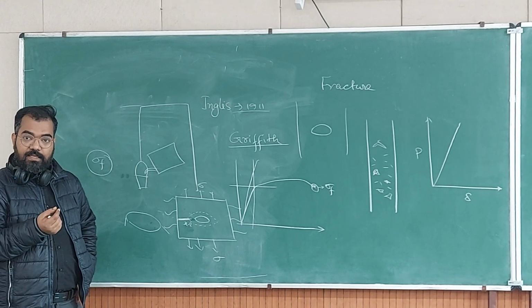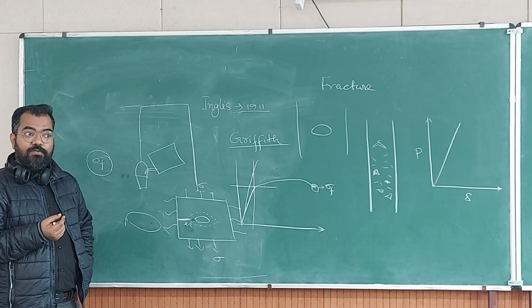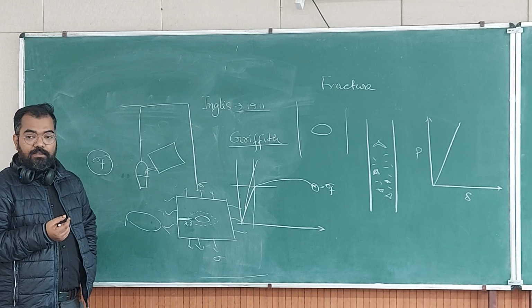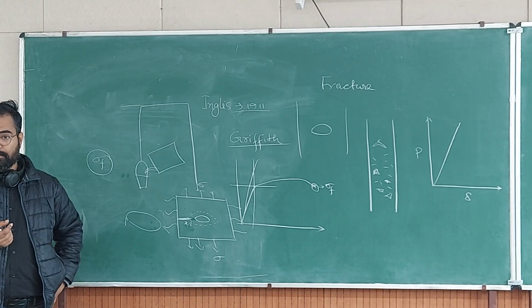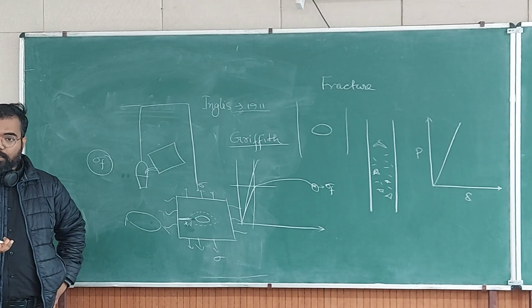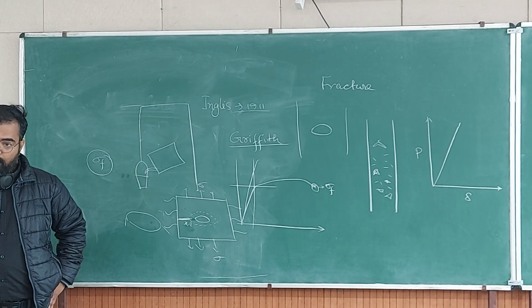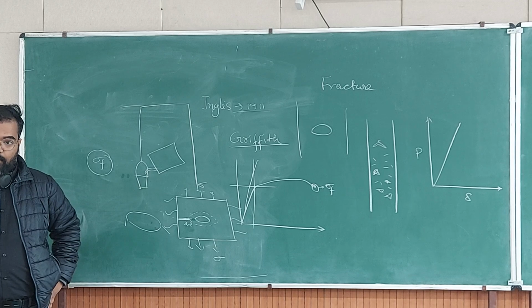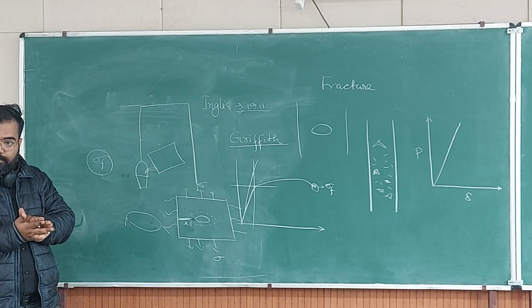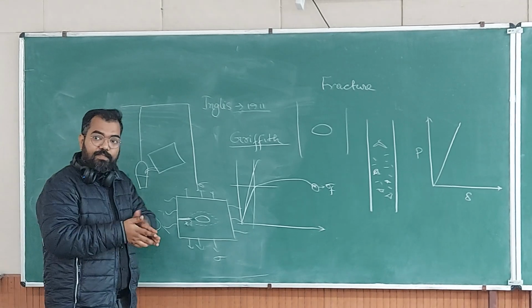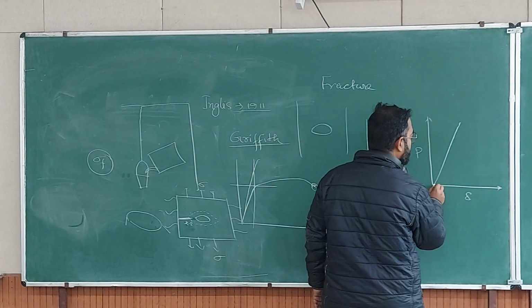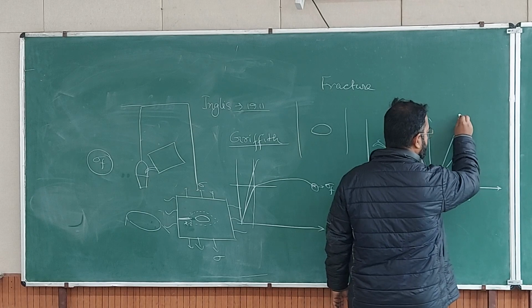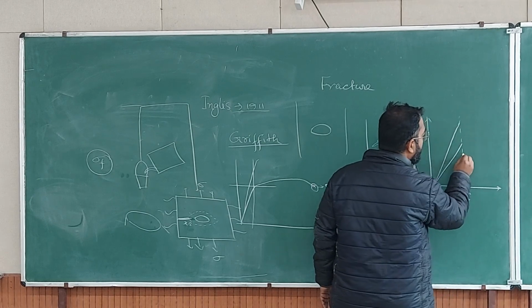Now the diameter has decreased, right? So for this decreased diameter, for the same amount of stress, is the force going to decrease or increase? It is going to decrease. Do you understand? Now there is less material which is intact, so you need less force. So there will be a drop in force, right, for the same amount of displacement.